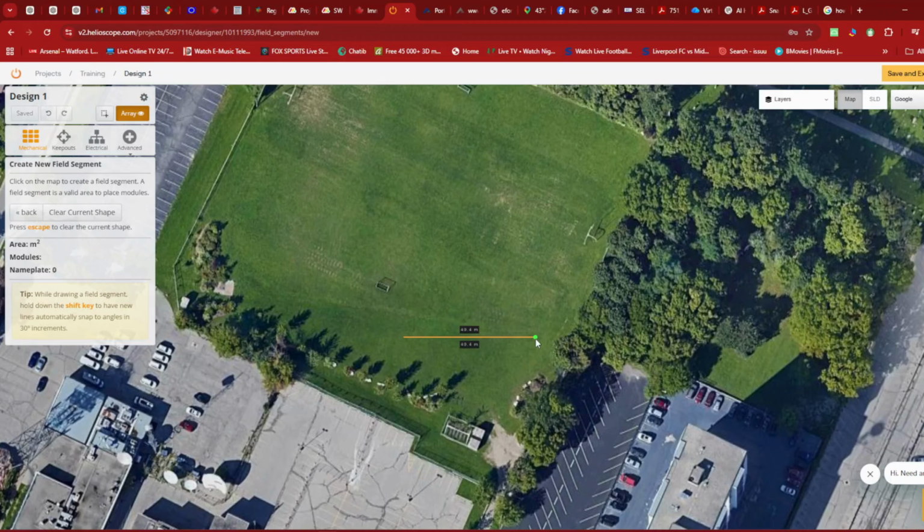That's what determines where to face your panels. The part of the sun which you need to check before you start your design, the part that the sun will take from east to west. So it's rising from east, setting out west, but going through the south, right?